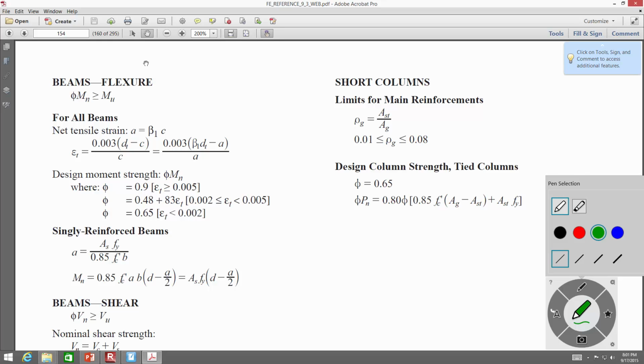Even without that, there's still quite a bit of calculation. Is there any way just to look at it? Can we make some assumptions? Well, there's a couple observations you can make. Number 1, the dead load was like 5 pounds per foot. It's nothing. This table weighs 5 pounds per foot, more than that, and we're talking about concrete beams. So you could almost just disregard the dead load of 5 pounds per foot and handle the point load by itself. That's a little bit of calculation you can save.